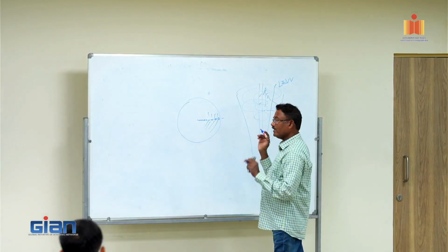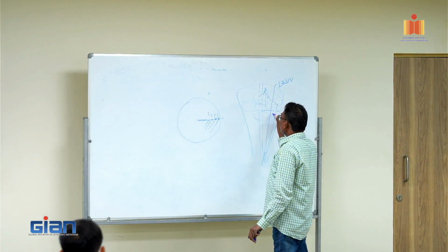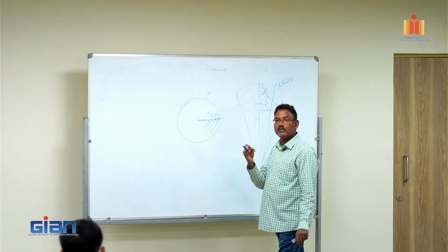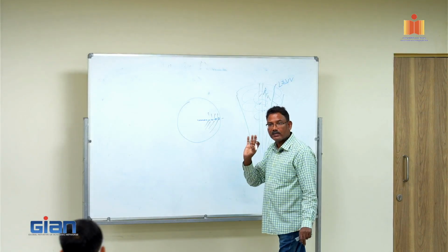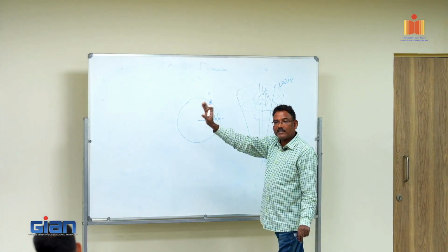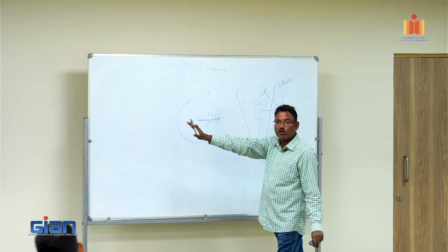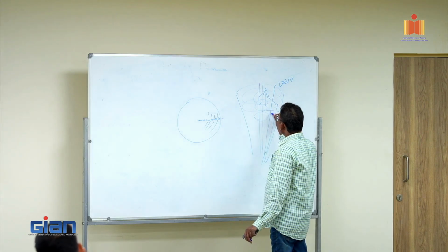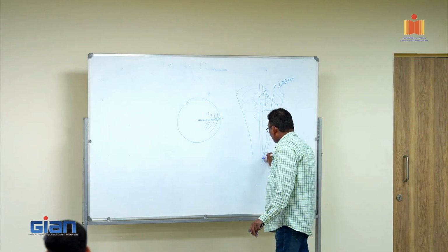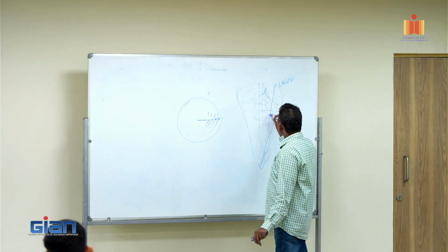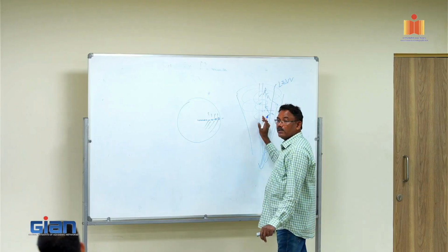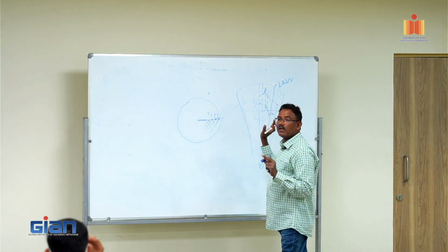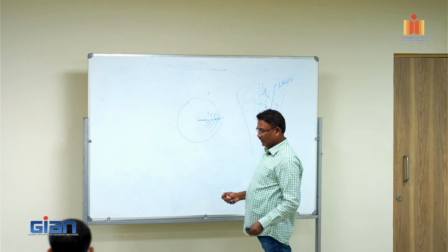Now the equilibrium orbit theory says that the particle's effective mass is accounted for because of size and density together, right? Whatever the component, it is subjected to centrifugal forces, turbulent dispersion, as well as drag forces. If the particle by any chance moves to this side, it reports to the underflow, and if it moves to this other side, it reports to the overflow. Now this is for a pure, same-density particle. When you have a multi-density particle, what happens?